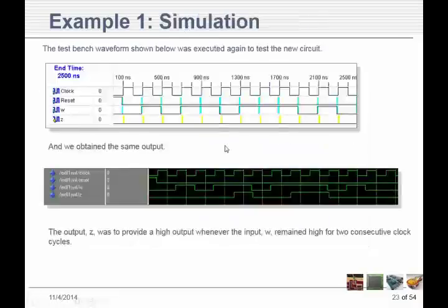I'm seeing some of these results where the output here is just a flat line. And then I look up at the reset, and the problem is that reset's holding it low the whole time, or holding it high the whole time. Watch out for that. Your whole test bench isn't doing you any good if you're using this one line to keep it high or low the whole time.